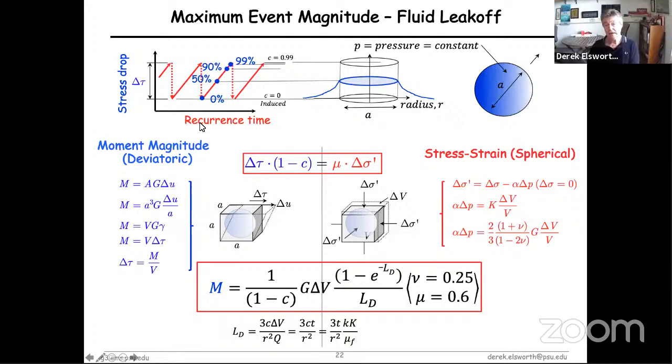Yeah, well, rate state friction behavior has been used as a very straightforward way, much less complex, for instance, than if you're working in a geotech program where you have lots of complex constitutive laws to describe behavior. Usually it's a very simple experiment, shearing of a sample. Usually experiments are done not in terms of stress control, but in terms of strain rate control, constant velocity perturbation. And it gives a very simple output, which gives you these second order friction effects that pick up this very definitive behavior of whether friction strength goes up or down as a function of velocity. So whether it's velocity weakening or velocity strengthening.